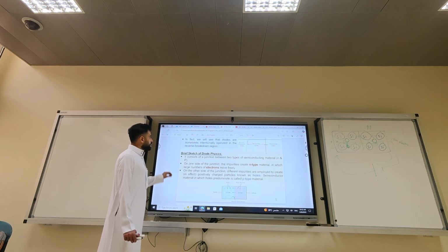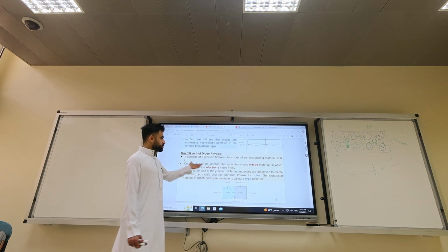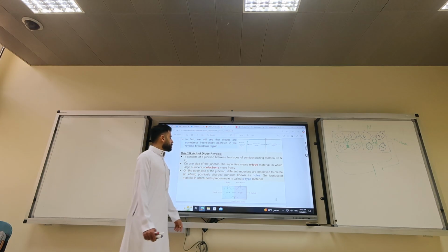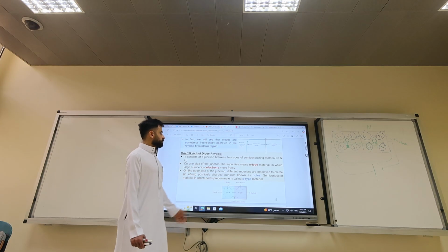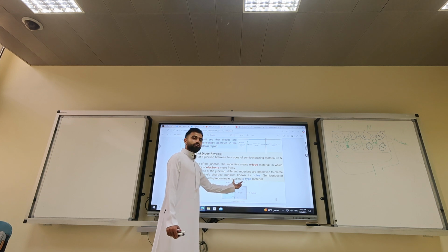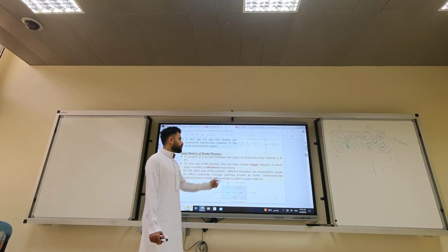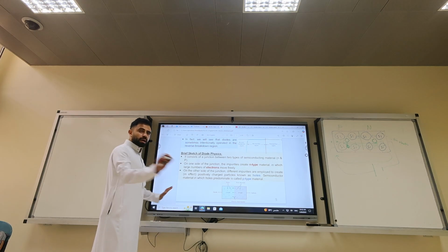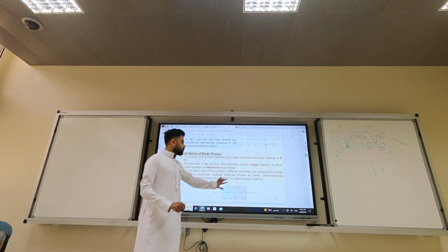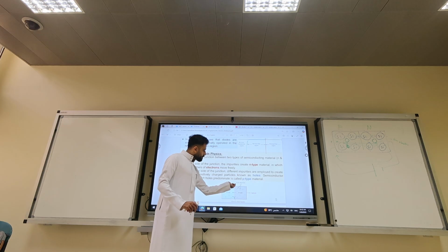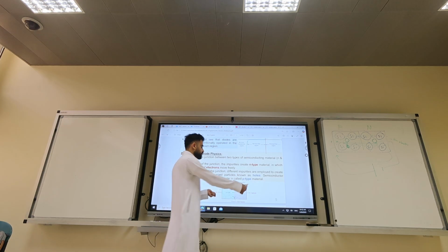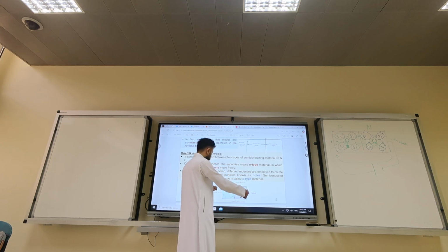And in summary, the diode consists of a junction between two types of semiconductor material. One has impurities for N-type, where you have more free electrons. The other, you will have more free holes. If you don't apply any voltage, nothing will happen, except you will have a very tiny 0.7 voltage here. So if you put a voltmeter and you measure it from anode to cathode, it will be plus 0.7.